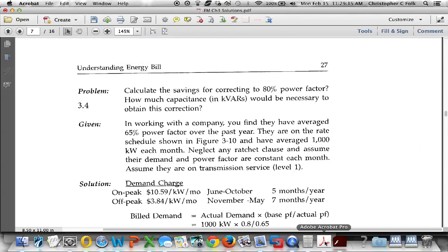If the ratio is less than 80% or 0.8, the utility companies can and may charge a penalty imposed on all purchased energy. So it boils down to the utility having to generate, in this case, our problem of 1,231 volt amps in order to sell 1,000 watts of energy. They really do have to use more fuel to do this.